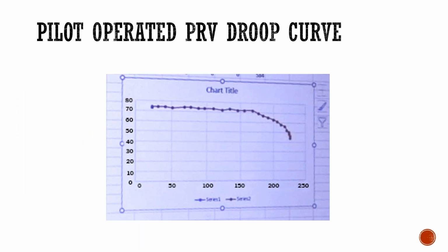So you can see here the flow curve. You can see that we're dead flat here for quite some time before it starts to droop off. So you've got a much wider range that you can operate in and maintain the accuracy of regulation that you require.